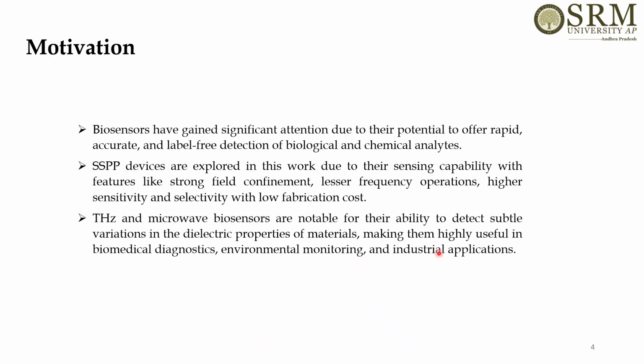The motivation behind surface plasmon polaritons is that they are gaining significant research interest in biosensing applications, for example to detect biological samples with rapid, accurate, and label-free detection. Also, SSPPs can be used for sensing because they have strong field confinement and work at lower frequencies, giving high sensitivity and selectivity with low fabrication cost.